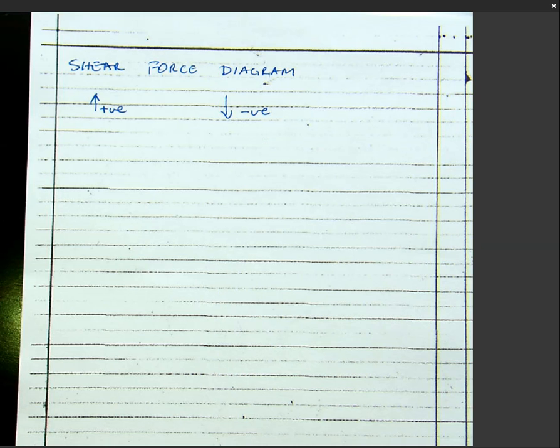If you look at the force that is going up, you're going to treat it as positive, although in real practice that is not very important. The most important thing is to be able to draw the shear force at that point. For the shear force diagram, the signs are not that important. They are mainly important when we are dealing with the bending moment diagram, because at a later stage when you are designing the beam, there's a different beam design for a positive moment to that of a negative moment. But when it comes to shear, shear is shear, regardless of whether it's negative or positive.